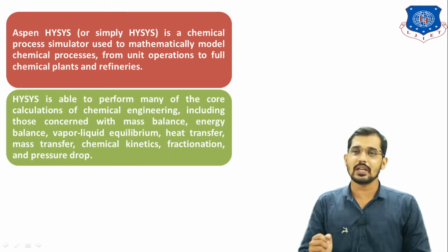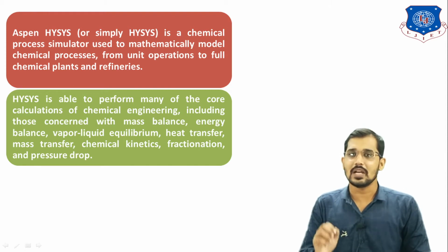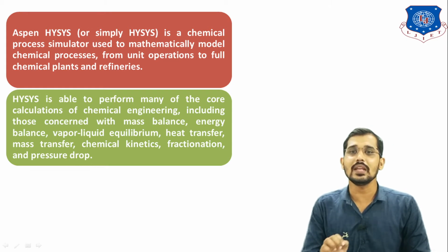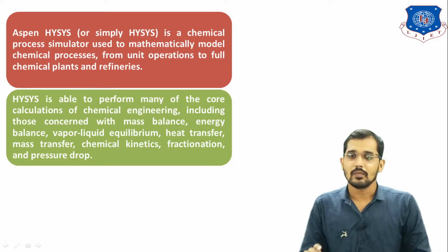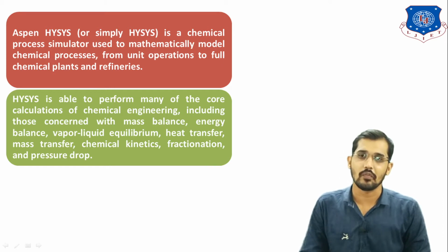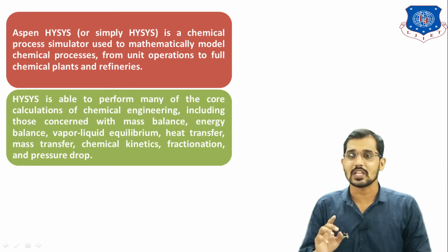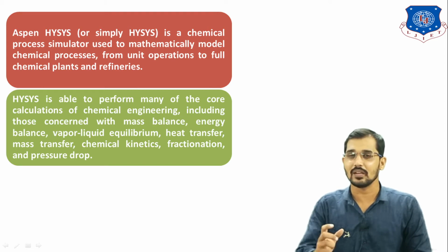After that, the next point related to HYSYS is HYSYS is able to perform many of the core calculations of chemical engineering, including those concerned with mass balances, energy balances, vapor liquid equilibrium, that is nothing but VLE data, heat transfer, mass transfer, chemical kinetics, or I can say fractionation and pressure drop. So all these calculations are possible in this HYSYS software. So by using HYSYS, we can do major applications which are involved in chemical processes. Now we will see how to simulate a gas liquid separator in HYSYS.